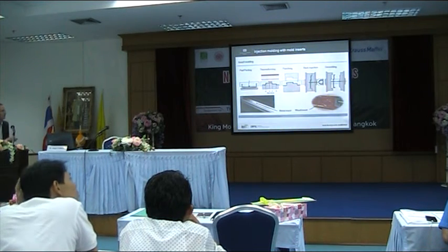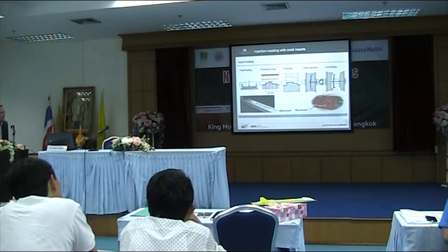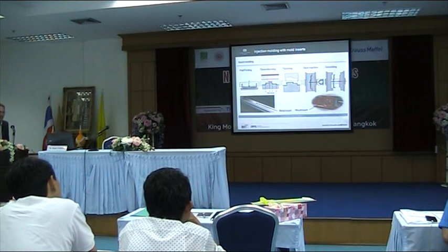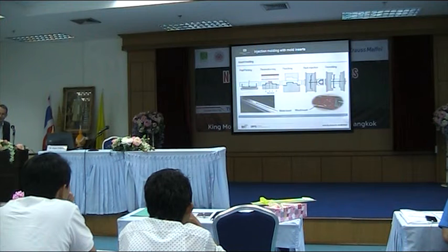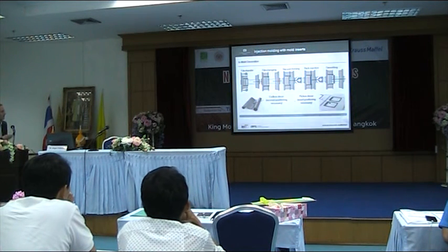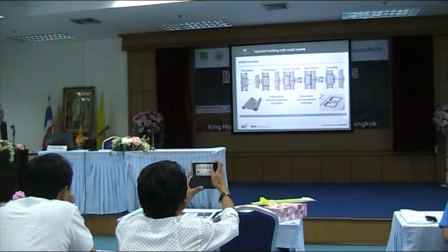You integrate it in the mold, you make some back injection, and then you have your demolding. These inserts can be natural materials, for example the really popular wood insert or veneer insert, and this will be something, as an automotive application, that the Wagenführer will say something about, and Caroline. This is the same with in-mold decoration with vacuum assistance, so you can fix the material at the mold cavity wall.